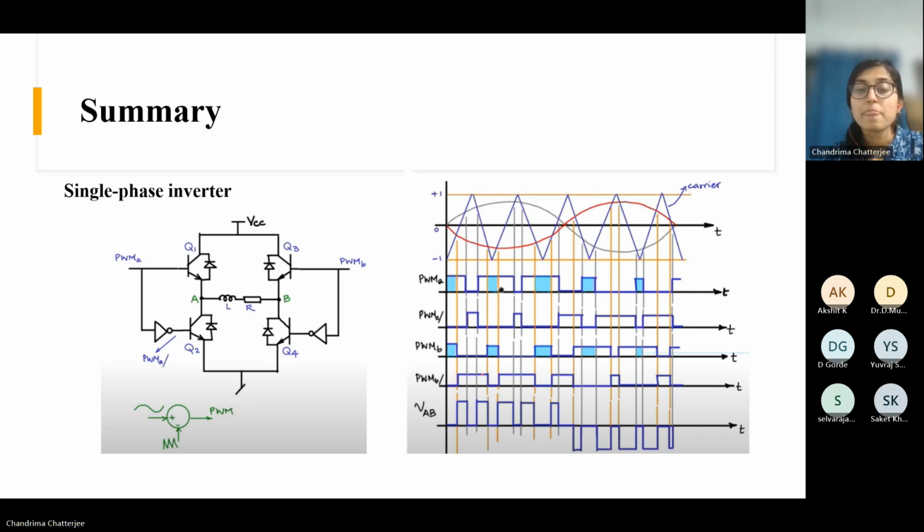So for unipolar SPWM, you see there are two sine waves. One like this, another 180-degree phase shifted inverted sine. The advantage is you get zero levels in the load voltage. You get plus VDC, and you also get zero level. In the positive half, you only get 0 and plus VDC, and in the negative half, you get 0 and minus VDC. So the instantaneous difference is less between the actual output and the pulse width modulated output. That's why the harmonic distortion is less for unipolar PWM, and the filter size will also reduce because the harmonic content is less here.